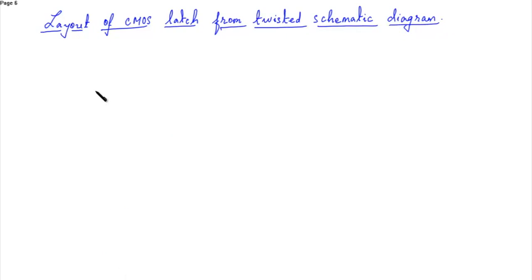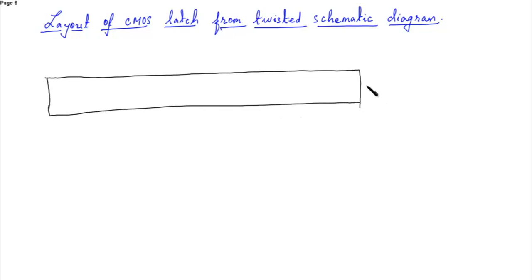So at first, from the previous schematic, which was drawn from the point of view to use a single N-well and a single P diffusion layer, with reference to it, we'll take a single N-well, and a single P diffusion layer.